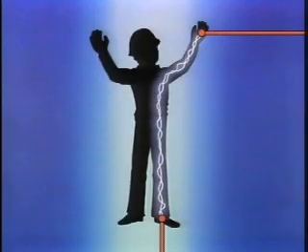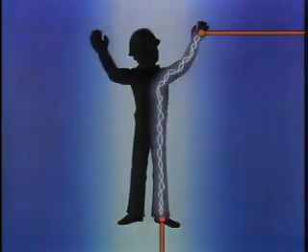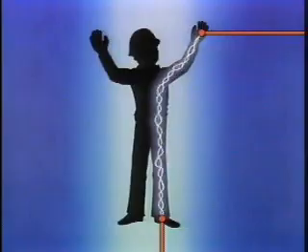The reason that the path current takes through a person's body can affect the severity of a shock is that some parts of the body are more vulnerable to the effects of current flow than others. For example, a relatively small amount of current flow through the heart is more dangerous than a larger amount of current flow that does not pass through the heart. In general, current will flow through all available paths, but most of the current will flow through the path of least resistance.